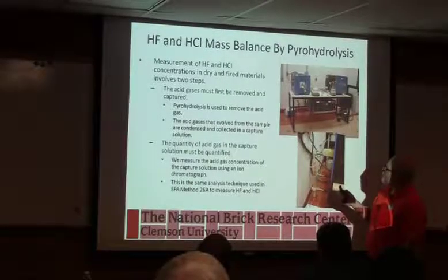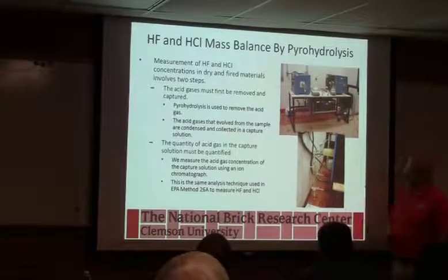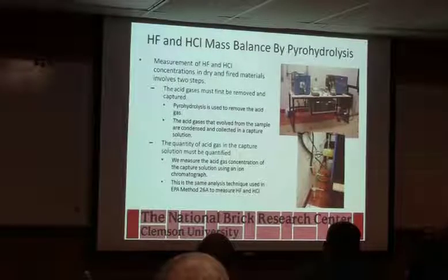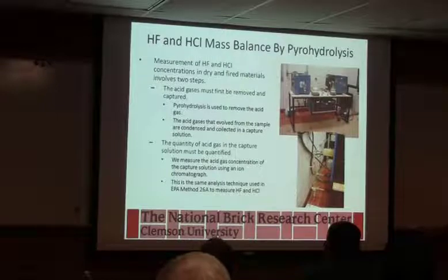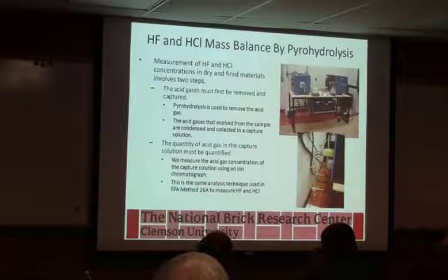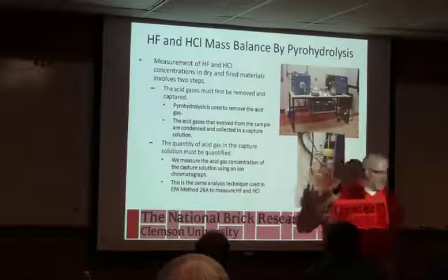We got steam flowing through. We catch the condensate off the backside of the furnace, and we can read that with another instrument. We use those ion chromatographs like I was telling you about for the soluble salt. They can measure really low levels of fluorine and chlorine, and it's similar to a stack test method, that analysis technique. Any of you ever seen stack testing in your plant?